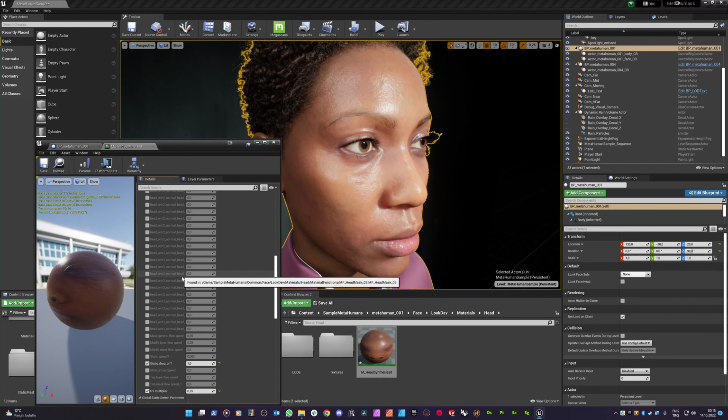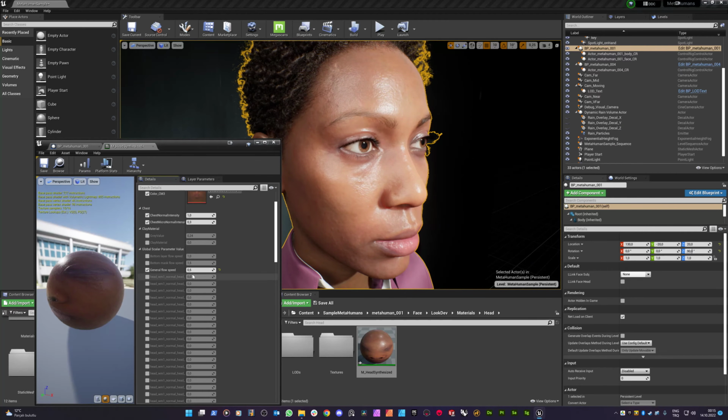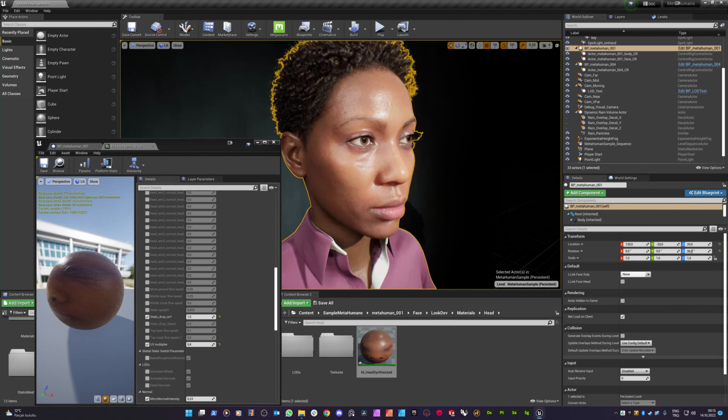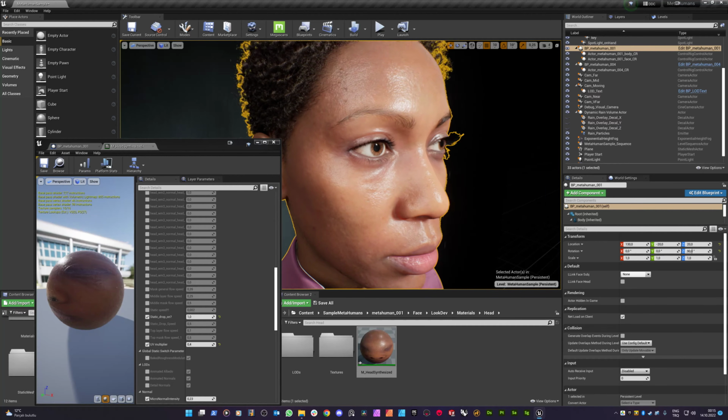Once you set the static drop mode to 1, I suggest you set the general flow speed to 0, which creates much more intense splashes or drops, and you can change the UV multiplier this way to get a better scale according to your model.